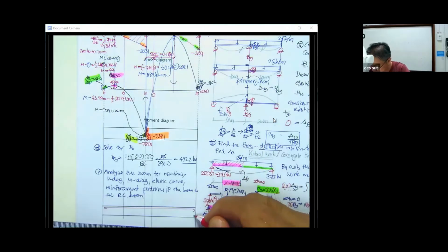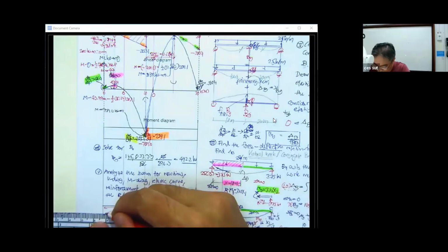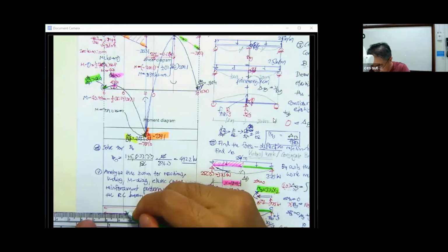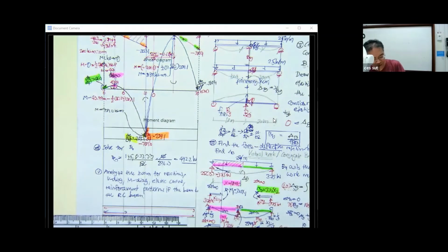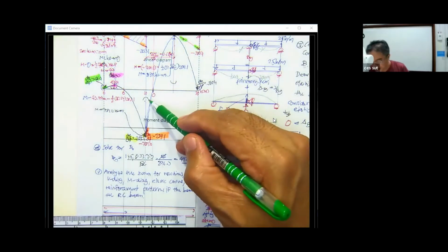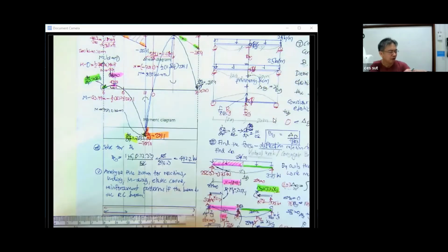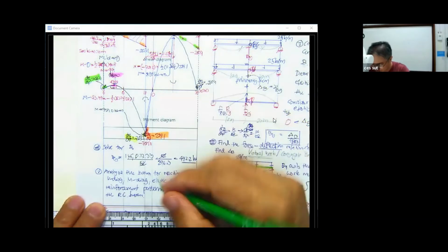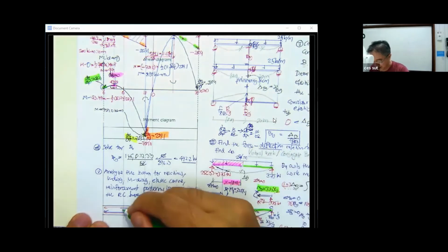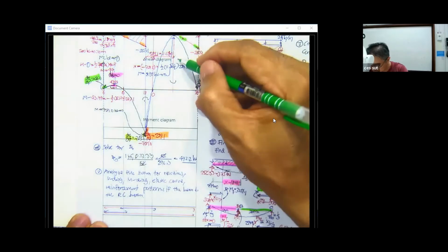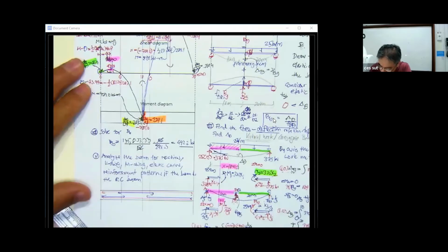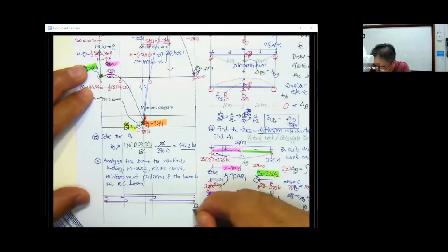Usually we are supposed to run all the reinforcement along the beam. That is for the stirrup, also for our ease of construction. And this is concave upward. So the beam must be reinforced more over here. The beam must be reinforced more over here. And then this is concave upward. Okay, so this portion is going to have the extra reinforcement like this. And this portion we will put the extra reinforcement like this. Okay, so this is going to be the pattern that we will put the reinforcement over our structure.